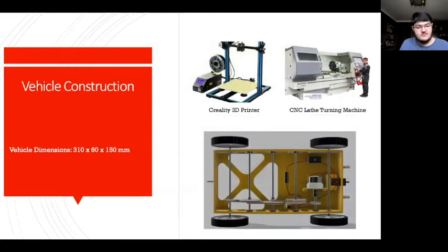Before assembling the vehicle, some components must be machined. Firstly, a 1 meter aluminium round bar will have to be cut into 6 145mm length bars, as they will be used as shafts to hold our pulley system. A CNC lathe turning machine will be used to accurately cut the aluminium bar into our desired lengths.